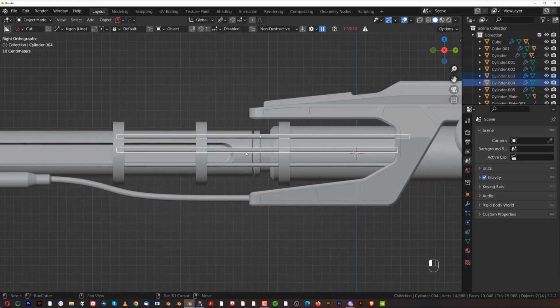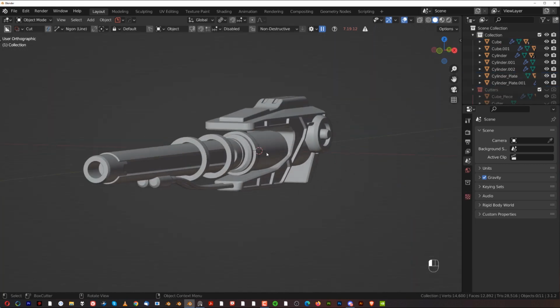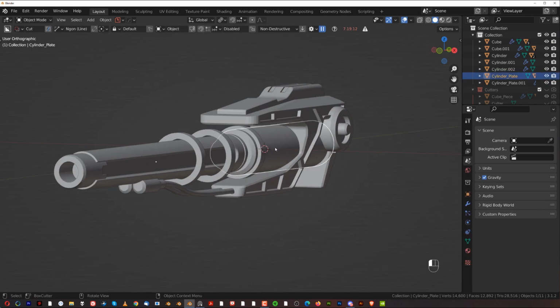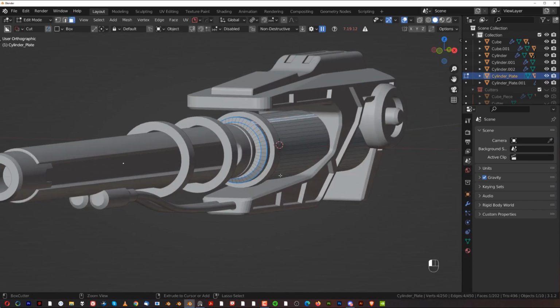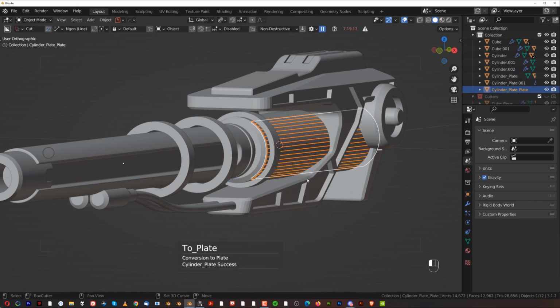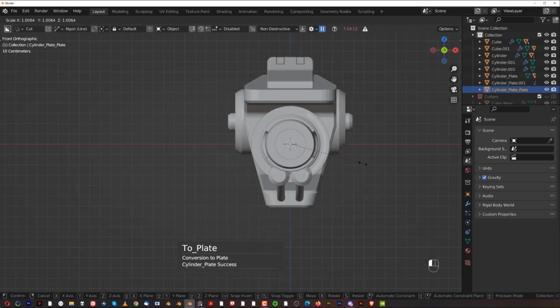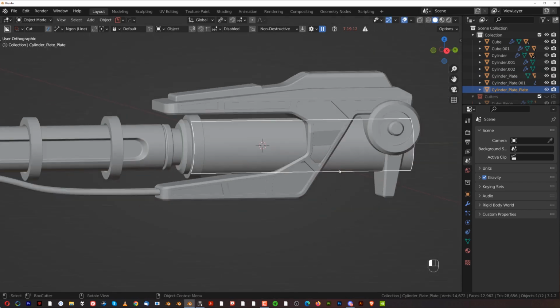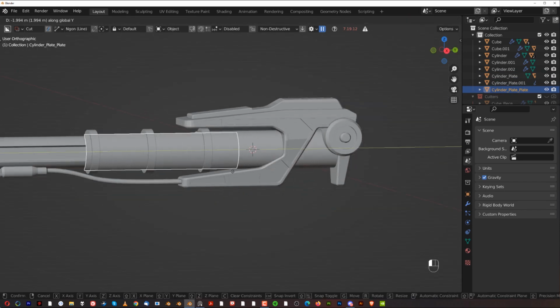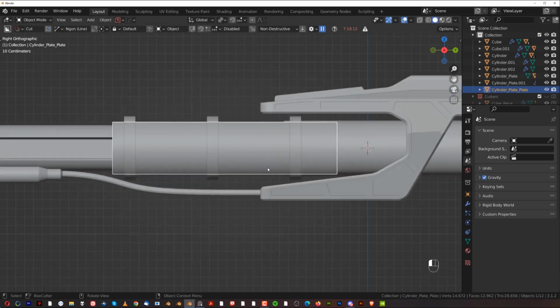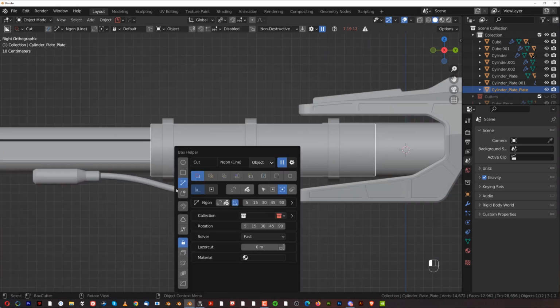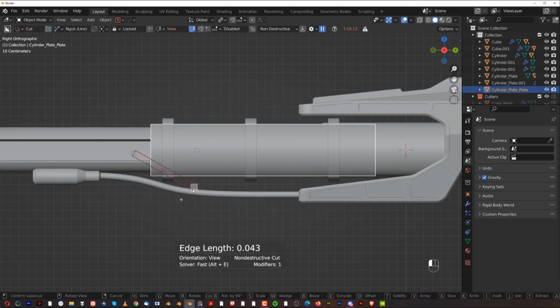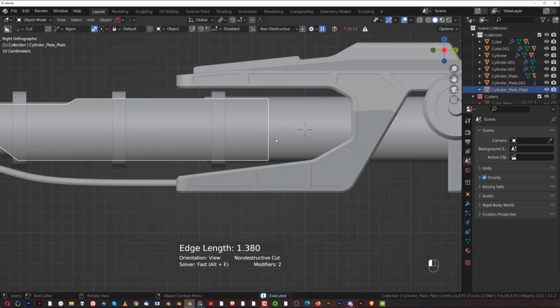So for example, if you don't like this one and you want something else, like some kind of shielding, it's really easy to do, guys, because all you do is grab these, you go Shift Curve Extract, you move it here, go here, you scale it out, and you move it forward. So GUI, move it forward here, okay, like this. And then what you can do, you can keep slicing it. So let's just go here to turn on the cyclic, and you can keep slicing this element here.